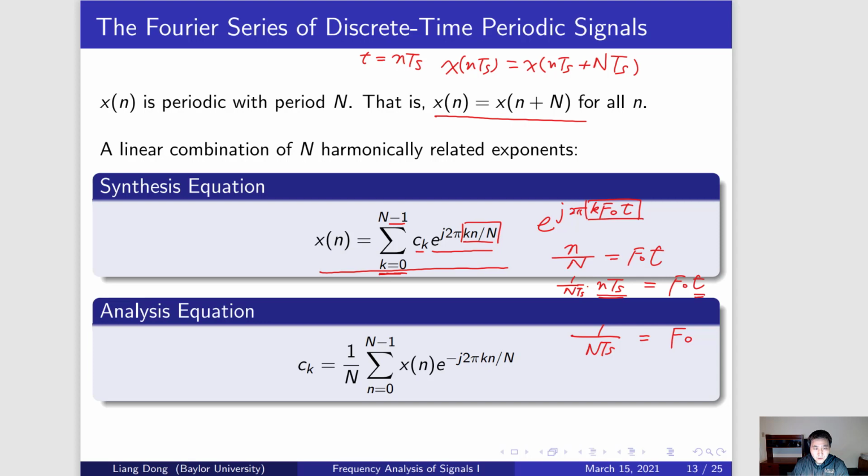Looking at a picture in the frequency domain, for the discretized synthesis, we have k from 0 all the way to N minus 1. So we have here, this is N. With this period, this frequency N will stand for the frequency in the continuous time periodic signal, that is fs, corresponding to the sampling frequency.